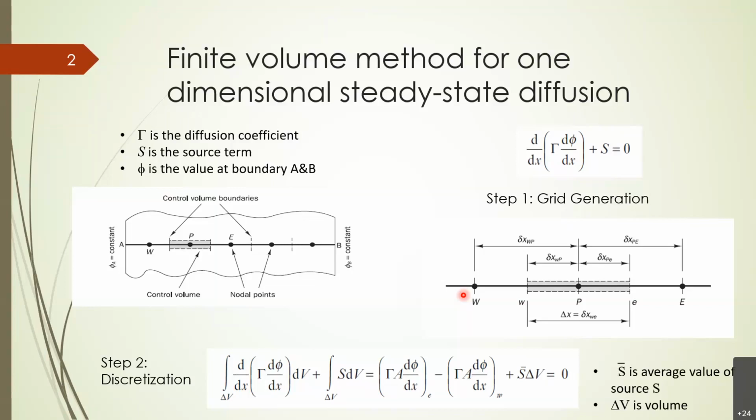So what we have over here is just the whole equations. Of course, when you want to introduce the source term, it needs to be done via a subroutine. Basically, it is a more detailed subroutine, usually a programming part, where we have to indicate to the software, I want my source term, this part of the problem, I want to introduce turbulence as my source term. This is where I want this turbulence to be included in the software, in the calculations.